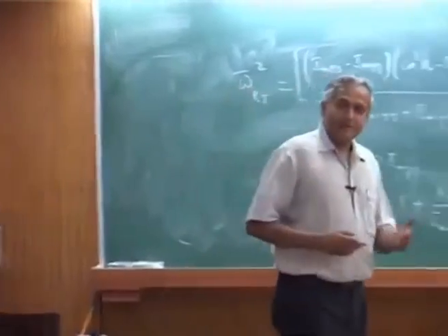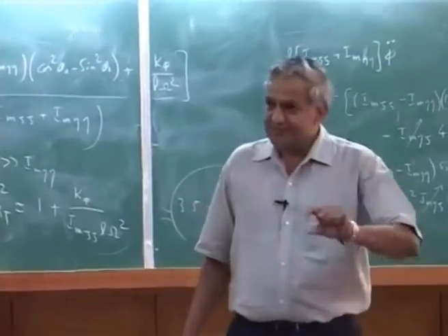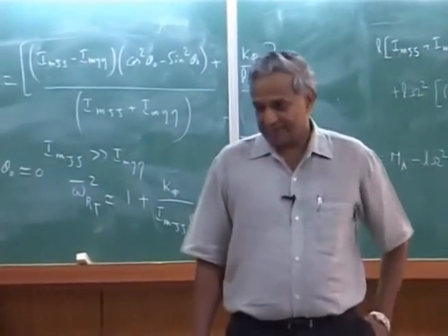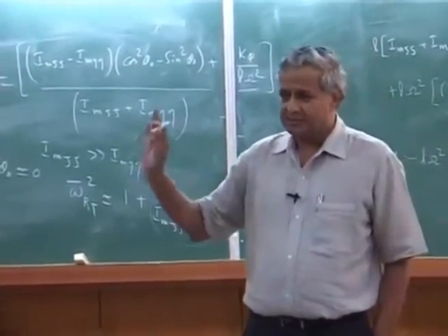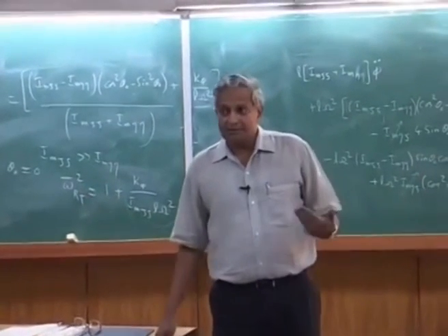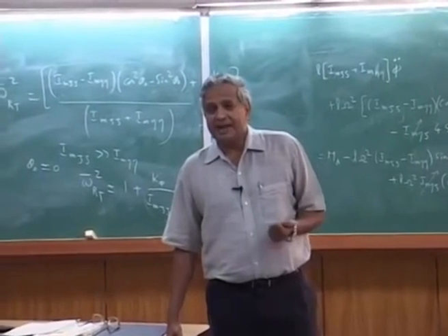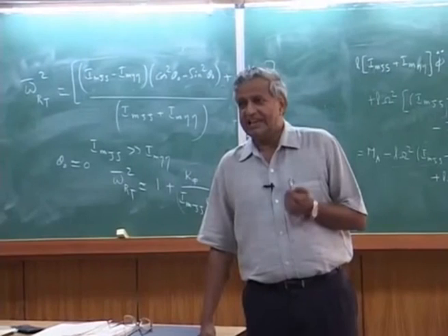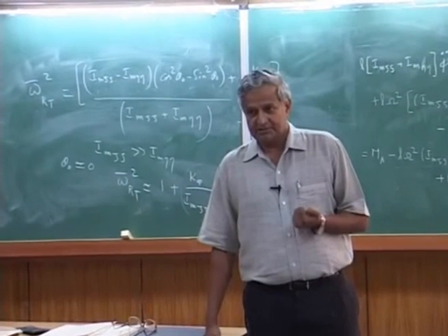Now, the treatment of the axial degree of freedom itself has several approaches. How it is done is, one is you make it as a rigid blade approximation. That's it. Why is it valid? The reason is axial stiffness, EA, is always much higher than bending and torsional stiffness.